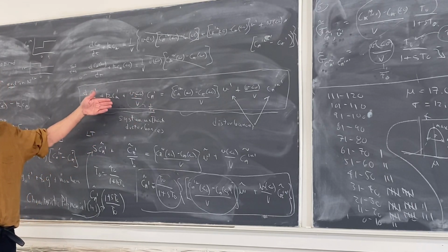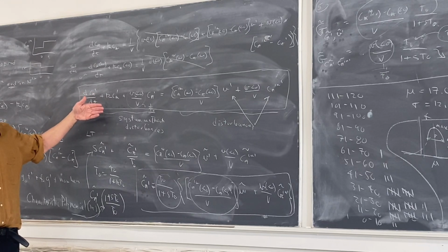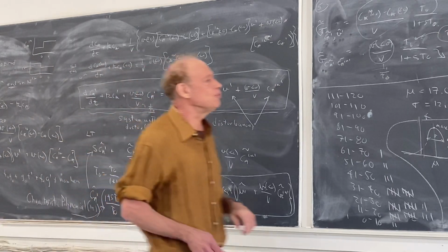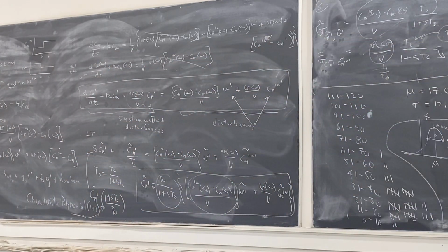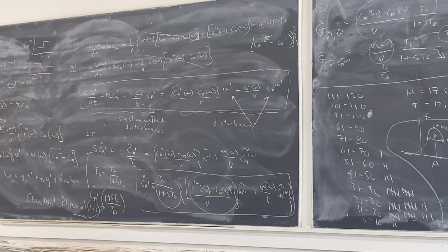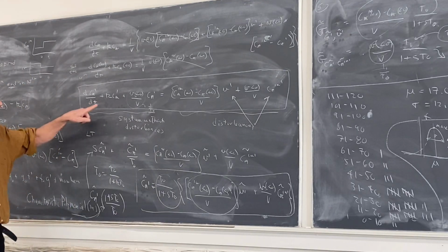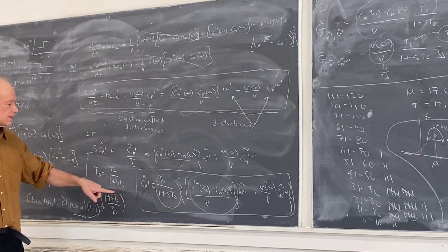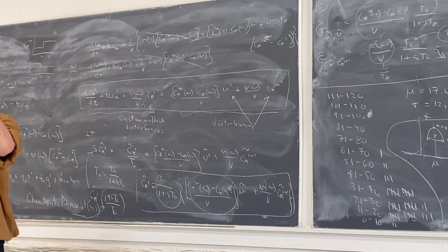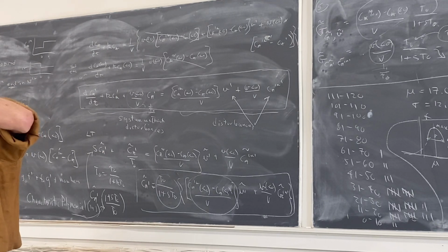The Laplace transform of the left side gives me the characteristic polynomial. When I solve for Ca prime tilde, I get in the denominator the characteristic polynomial. And it's the denominator whose roots we look at to get the stability.